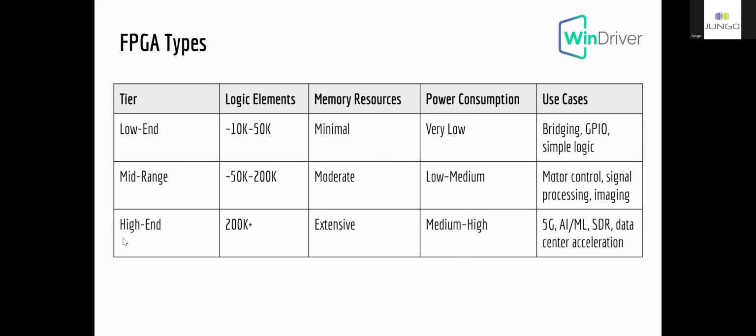And the high-end FPGAs have more than 200K logic elements. They use extensive memory resources. Their power consumption is medium to high, and they're used for 5G technology, AI or machine learning, data center acceleration, etc. So before even talking about drivers, one must know there are different types and tiers of FPGA. And maybe the first thing you need to ask yourself is what is the scope and what will suit you best.